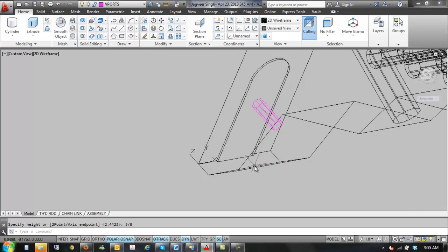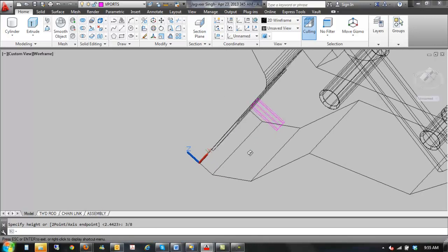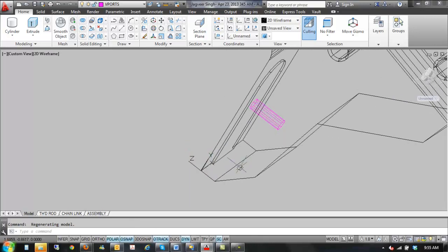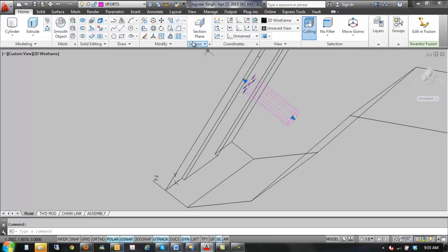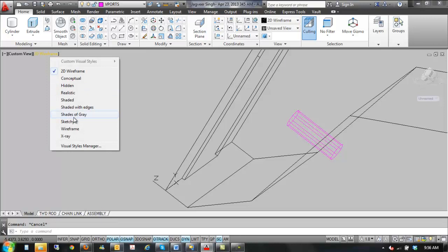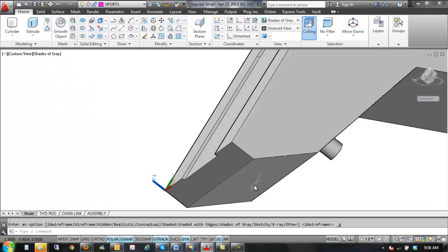Now, it's not quite in the right spot. It's flush with this surface, but I'm measuring from this corner. So I came in the 3/4, and it's perpendicular to this surface. So that's why I've created it where I have. And then what I'm going to do is take it and move it from here to the end of itself. I just know that if I look at it now, it's poking out the surface, right? Which is what I want.